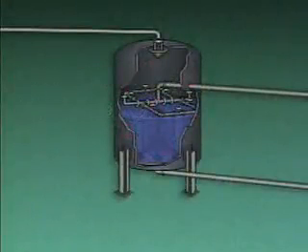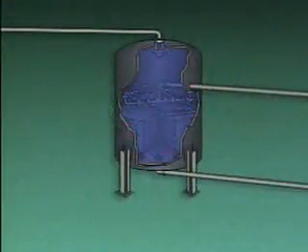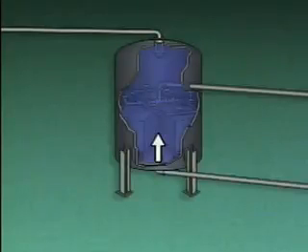During backwashing, water is pumped into the softener through the water outlet. As the water passes through the resin bed, it carries any suspended solids that are trapped among the resin beads out of the softener through the water inlet.